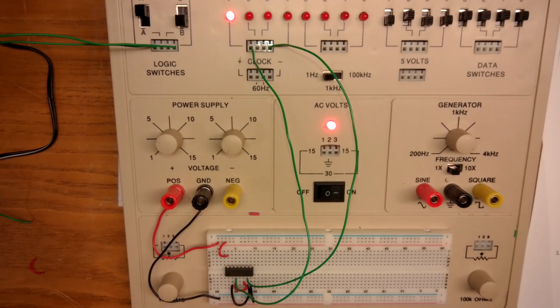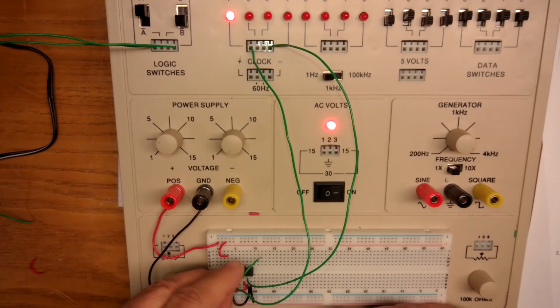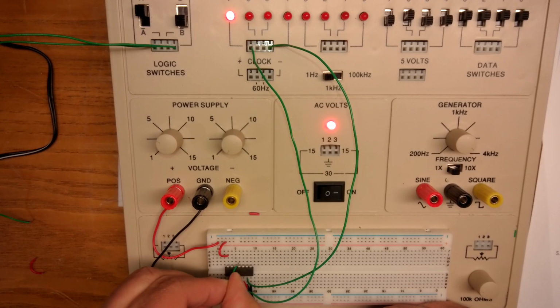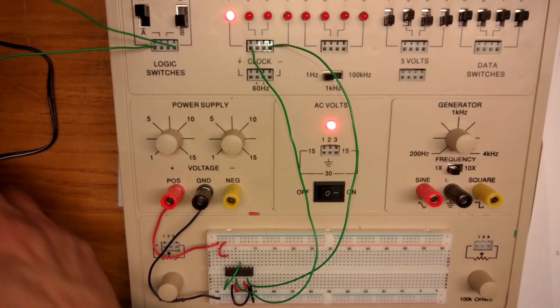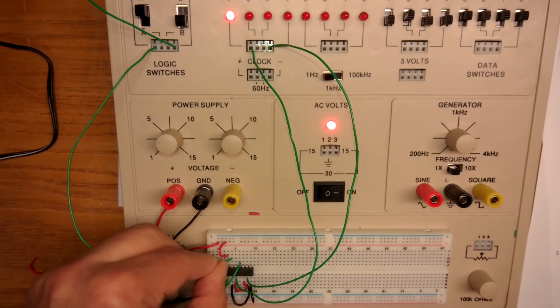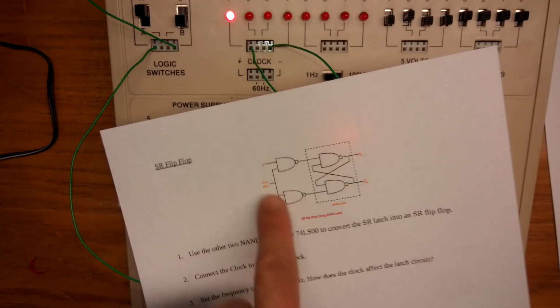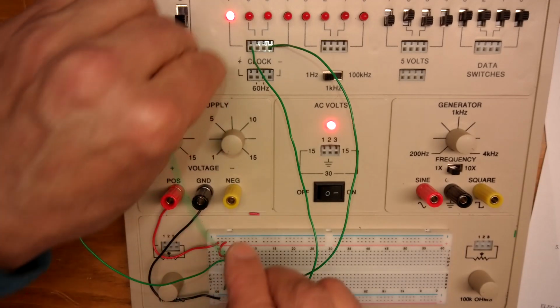Okay, these are a little longer wires than I'd want, but they'll hop back over and do the job. So this input comes from the output from this buffering NAND gate on the far side. The input to that NAND gate is S, so I'll take it using A in place of S, or for S. And the other input is the clock. So we'll put a wire over here for the clock. So let's take the clock down.